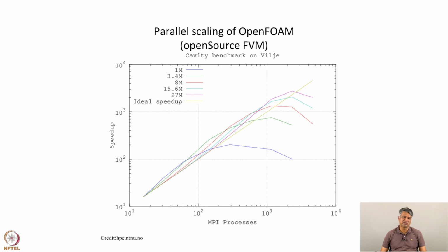There's another curious thing you will see in the initial part of this scaling study: the speedups are showing superlinear scalability, in the sense that they seem to be working at more than 100% efficiency. This is because of the trick of strong scaling, where you're reducing the number of degrees of freedom per processor as you're increasing the processor count.